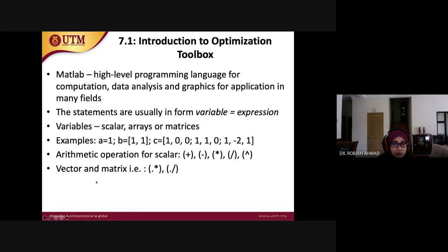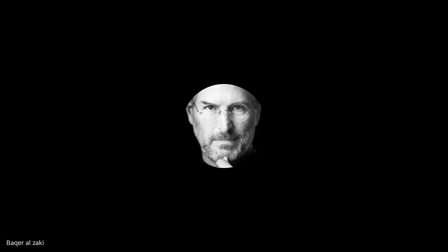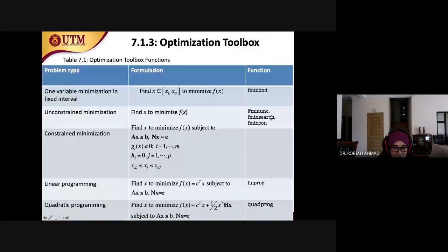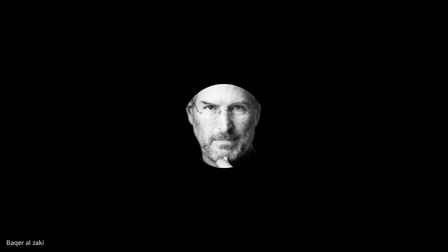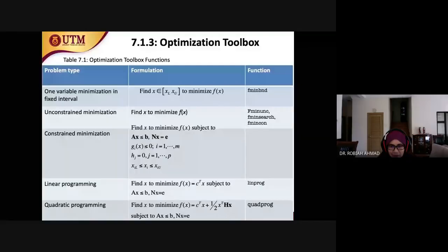Okay. So there is also fminunc, fminsearch, and fmincon. So I think we will look into fminsearch and fmincon. Okay. And then one is for unconstrained, meaning that you don't have the constraint that we looked into before, right? Okay, so just simply a function like the graph that I showed you before. So simply find x where f(x) equals the minimum point. So no constraint. So we can use fminunc, fminsearch. I think fmincon is for constraint. Sorry, fmincon is supposed to be down.